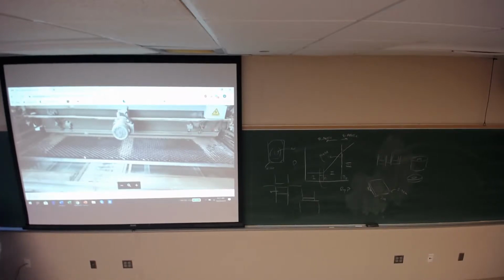By doing this, your segregation by size is limited to a very small area. Your non-uniformity will be linked to the size of this little volume that you're making. The consequence is that your die fill becomes remarkably uniform over a very large area.